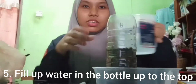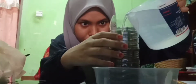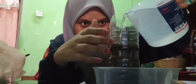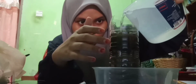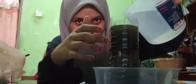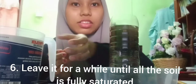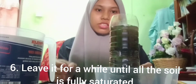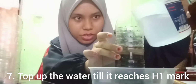After that, fill up water in the bottle up to the top. Leave it for a while until all the soil is fully saturated. Top up the water till it reaches H1.